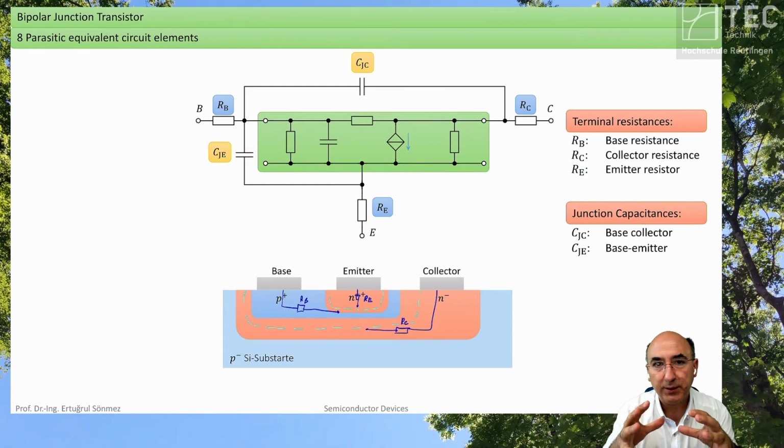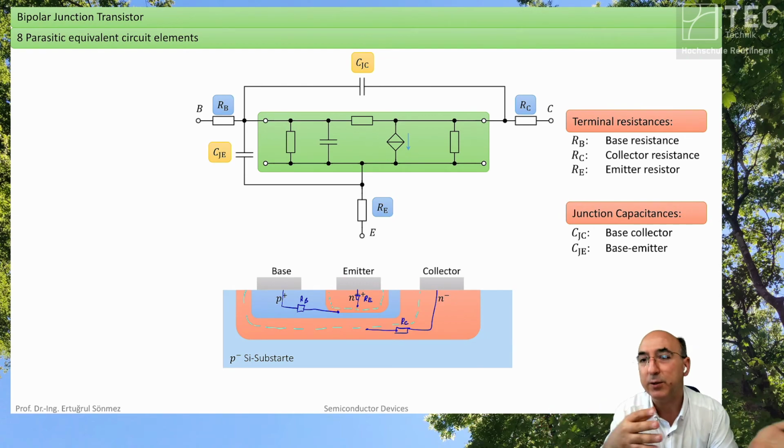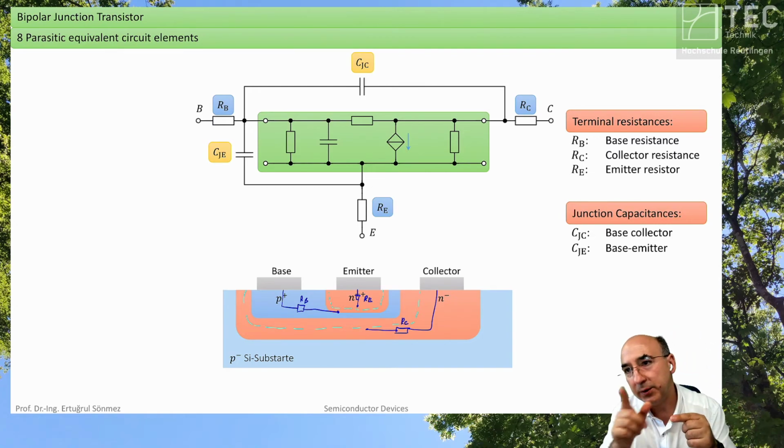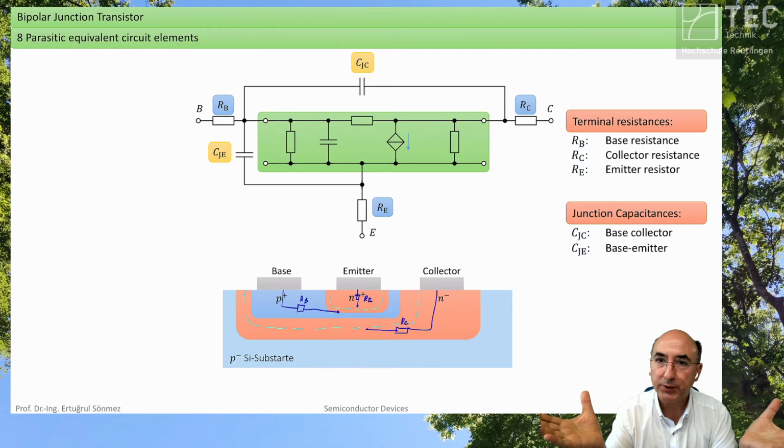You put together these devices and you have p-n junctions. You put a third one, then you have an n-p-n junction, then you have a bipolar. Under a certain condition a bipolar operates as a transistor: you have to make the base small in width to be able to transit all the injected charges. So we have a bipolar transistor.